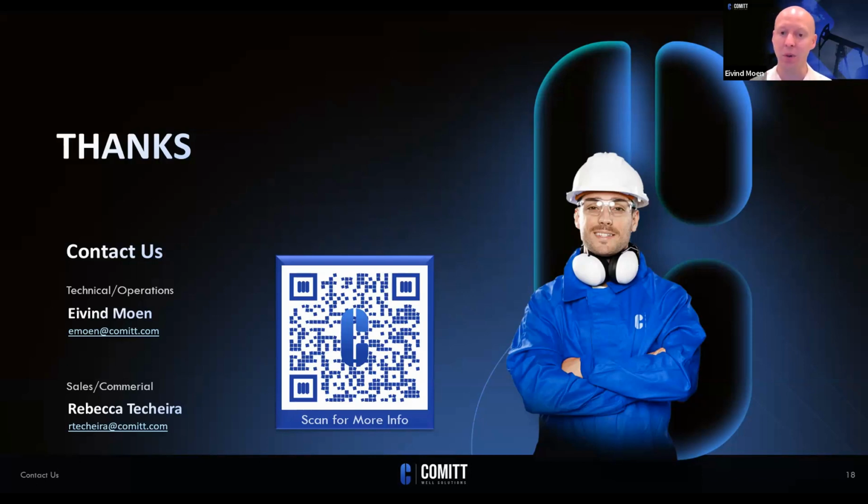But it's a good question, because especially if you're pumping proppant, you want to make sure you have sufficient rate. And the way we've done some proppant jobs, the tool is designed for that. We can pump a fair amount of proppant through this. Operationally, that is a more complex job, but we talked about cross communication that we see on our gauges as well. Pumping acid, we're not really seeing any operational issues from cross communication. With sand, that's a whole different issue. So at that point, we want to make sure we have a well where we can get rid of the sand. We want to have all the contingencies in place, but it is definitely possible to pump sand.